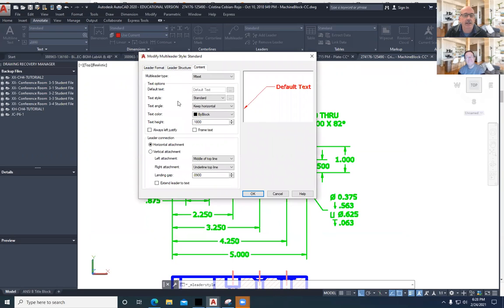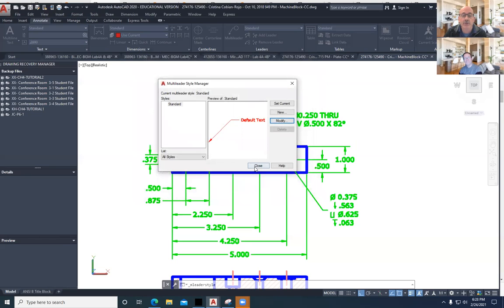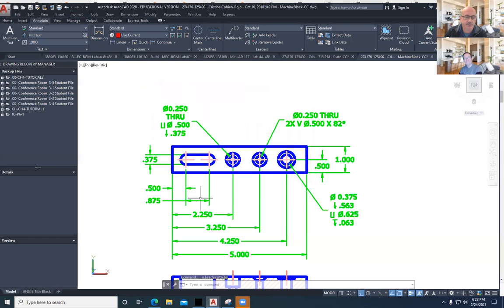And when we get into the content, we'll use these different text styles and text heights. If I wanted to tweak this and fix it, I could say 0.125. This one is not per the ASME Y14.2 standard. It's a little too big. Is anybody going to notice the text that's slightly off? Probably not. But they will notice if you are missing a dimension.